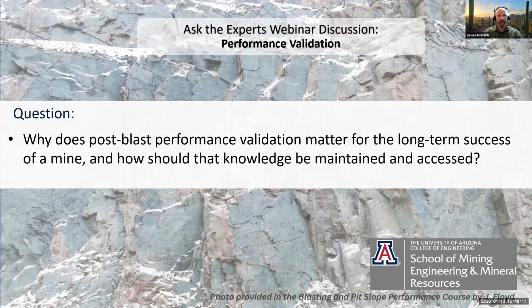Phil here. I just might comment that we haven't mentioned the dreaded words QA/QC, and I think good QA/QC programs to make sure that you're actually doing all the things out in the field that you had intended to do, including the control of blast hole depths, particularly close to slopes and your final berms, are important.